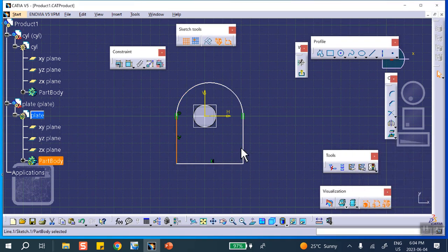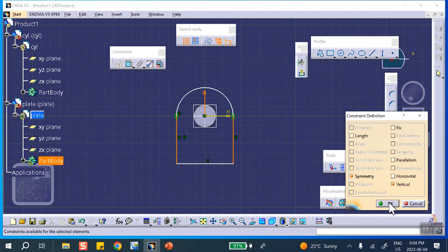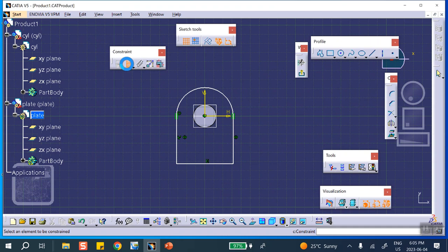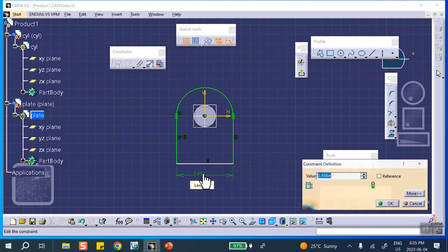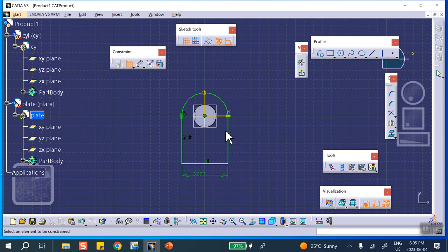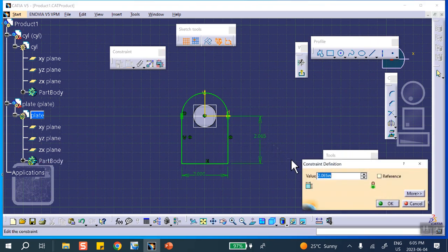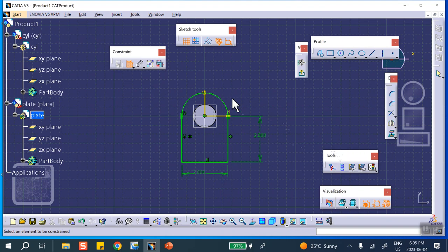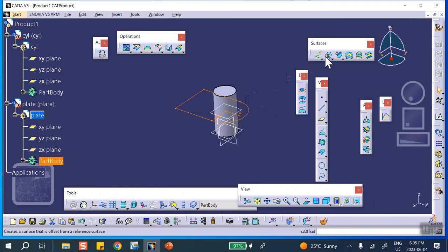So let's see now, the left line, control, right line, control, middle axis, control, right. We make it symmetric. Then dimension these, I believe this was 2. Okay. And exit. Now we can fill this. Here, fill, F-I-L-L.